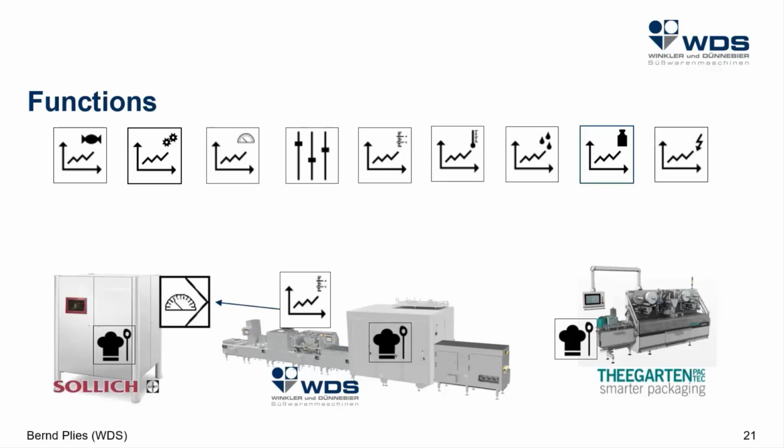The switching valves or the speed of the supplying pump may be controlled, for example. In the demonstration model, the valves are switched on and off depending on the filling level from the WDS hopper. In a similar way, a function has been integrated so that the WDS molding line adapts to the filling level of the packaging line's buffer store. That means the line speed is regulated automatically within the predetermined limits of WDS.